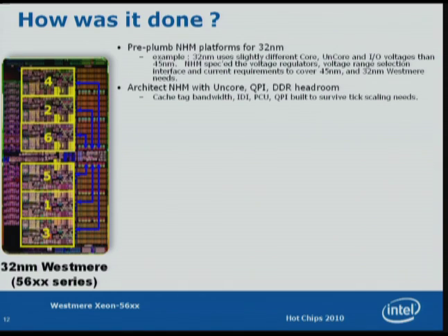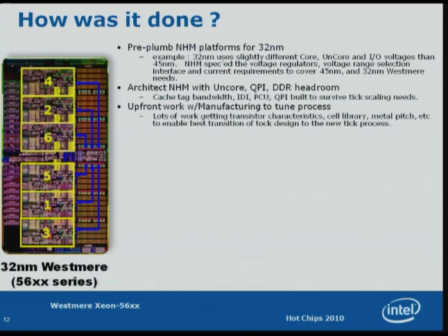The key here is the voltage frequency jump between cores and uncore. It happens right at each of these core interfaces here. The cores are sitting in their own voltage domains, and the core voltage and frequency can be moved around with respect to the uncore. There's a skew tolerant interface in there that's still low latency. That's how we jump back and forth between the domains here, and we can therefore move the frequency of the uncore up or down in the Nehalem products or in the Westmere products as needed for the bandwidth capabilities.